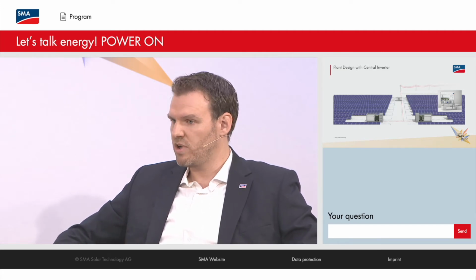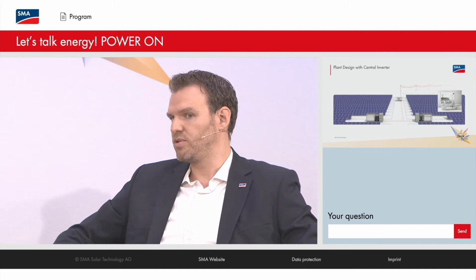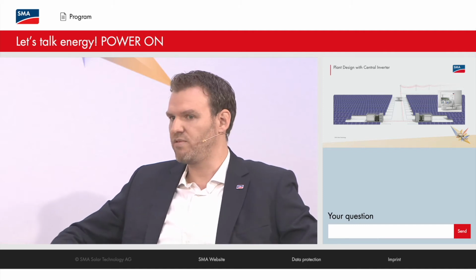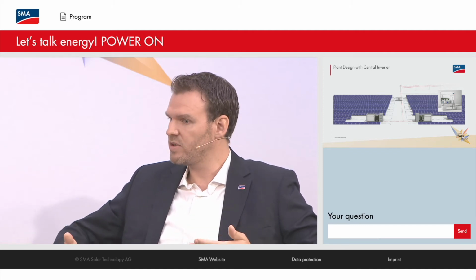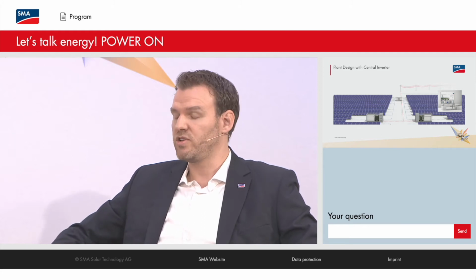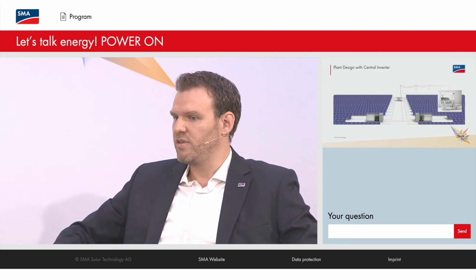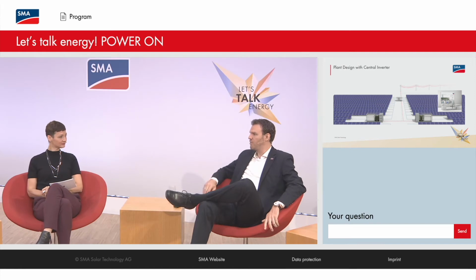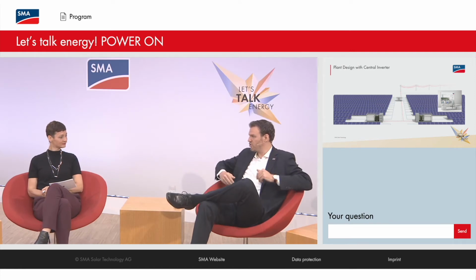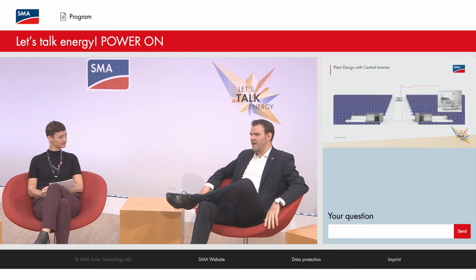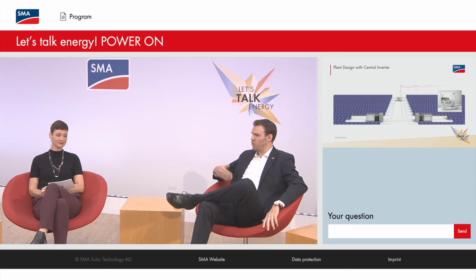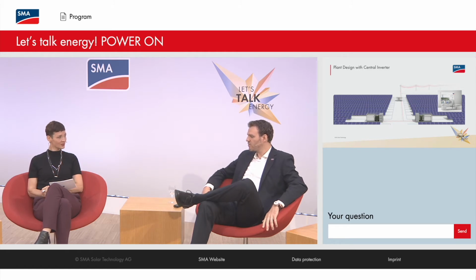And this becomes really interesting for the levelized cost of electricity, because especially here in Germany, not every day is very sunny, so we have very cloudy weather. So over the course of the year, it actually is interesting to oversize, and this typical bell curve becomes wider, so the shoulders get wider. And this extra yield for the project is beneficial, up to the point where you invest more in panels than you get back in additional yield.